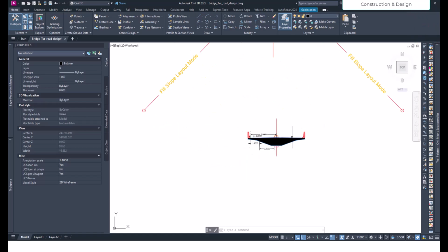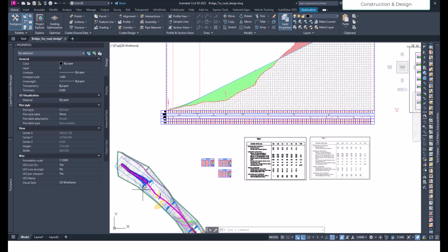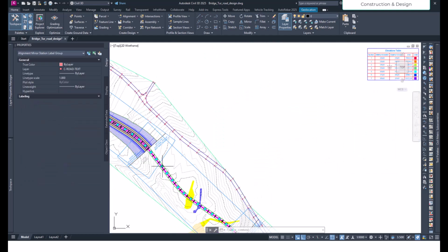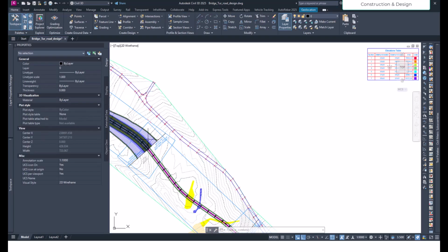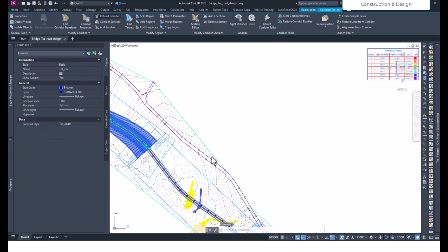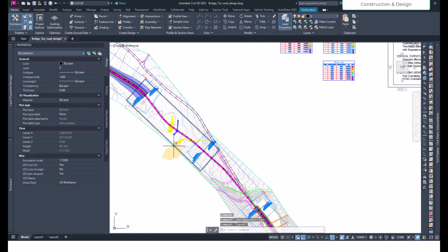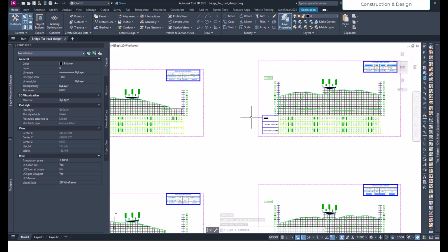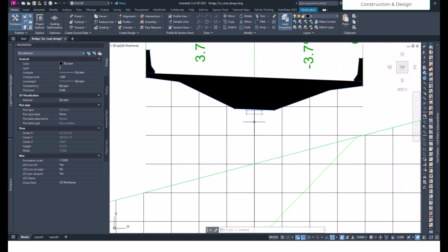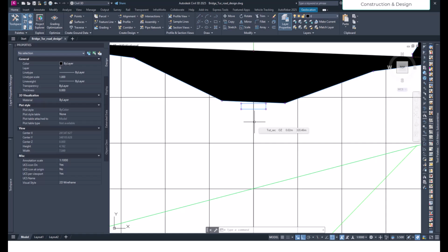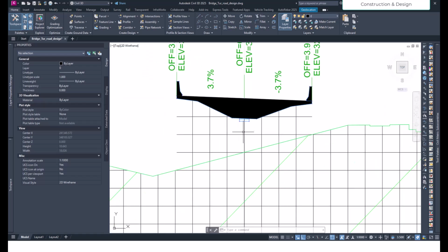Now what you can do is select the corridor and reveal the corridor. Once it's revealed, you go to the cross section to check it. It's 300, so we go somewhere here, and you see it's there. Even for this, the super elevation has been applied. You see the super elevation has been applied.